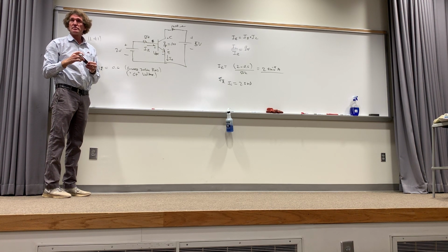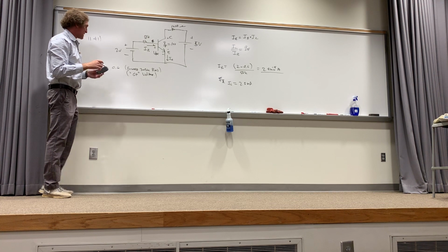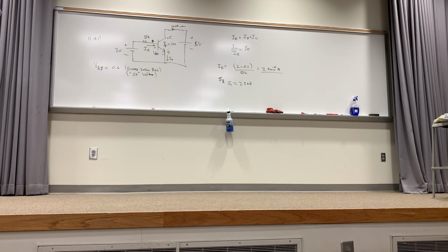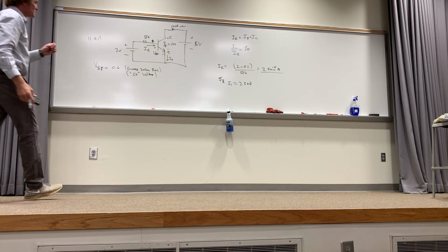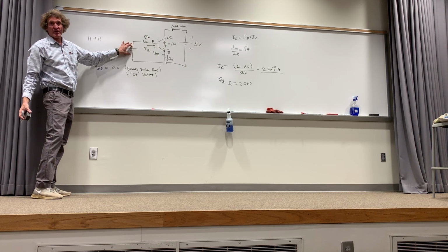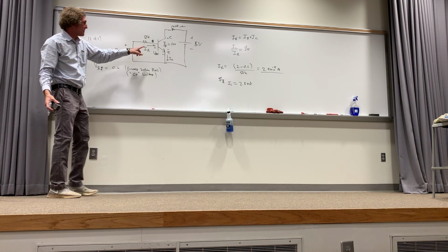What's the writing say next to the 0.6? That's just the junction bias. It's the on voltage. I called it the on voltage. It's how much you have to have before current will flow in that transistor. If, for instance, this voltage was 0.2 volts, nothing would happen. 0.3, nothing would happen. Got me? You have to have at least this voltage there.